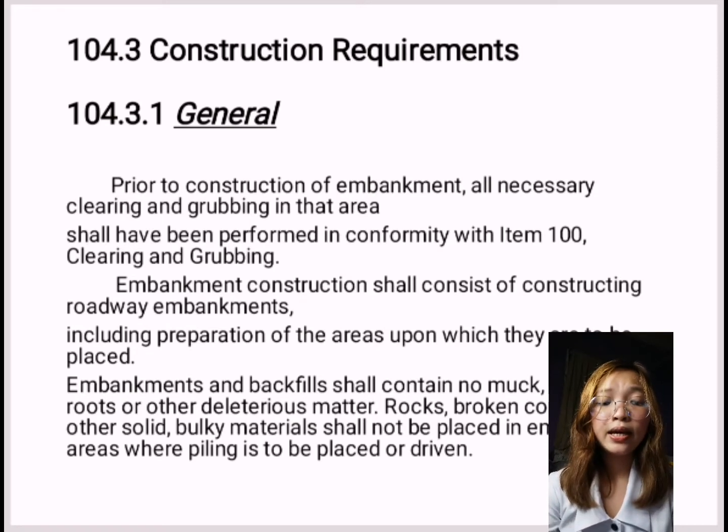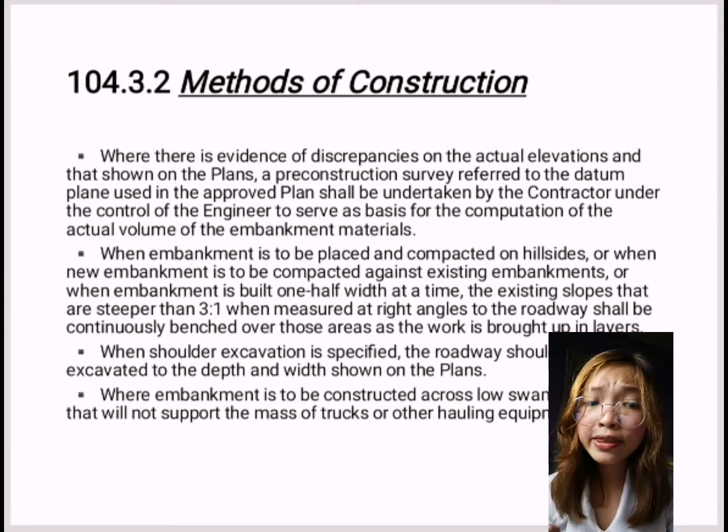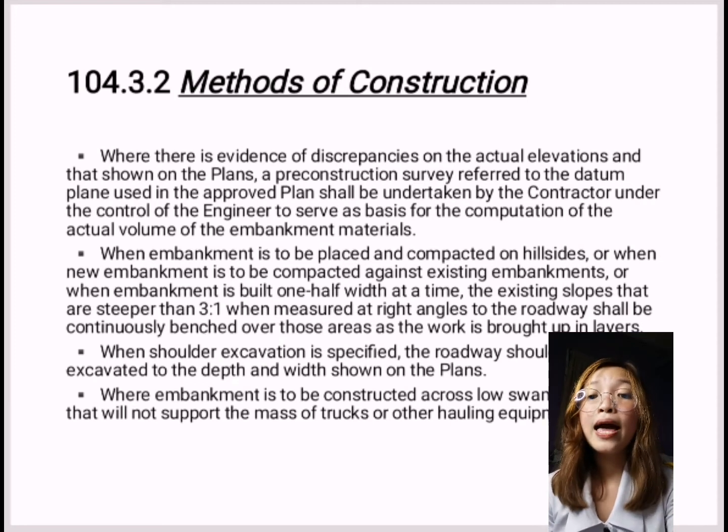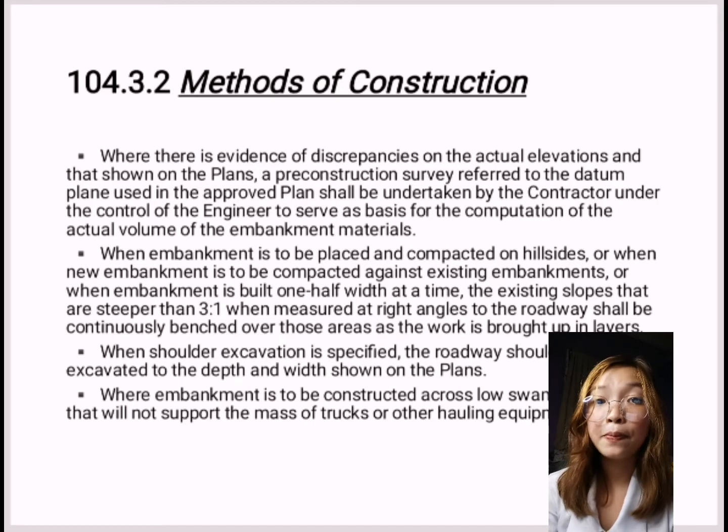So next is the item number 104.3.2, or the methods of construction. Where there is evidence of discrepancies in the actual elevations shown on the plans, a pre-construction survey referred to the datum plane used in the approved plan shall be undertaken by the contractor under the control of the engineer to serve as basis for the computation of the actual volume of the embankment materials.